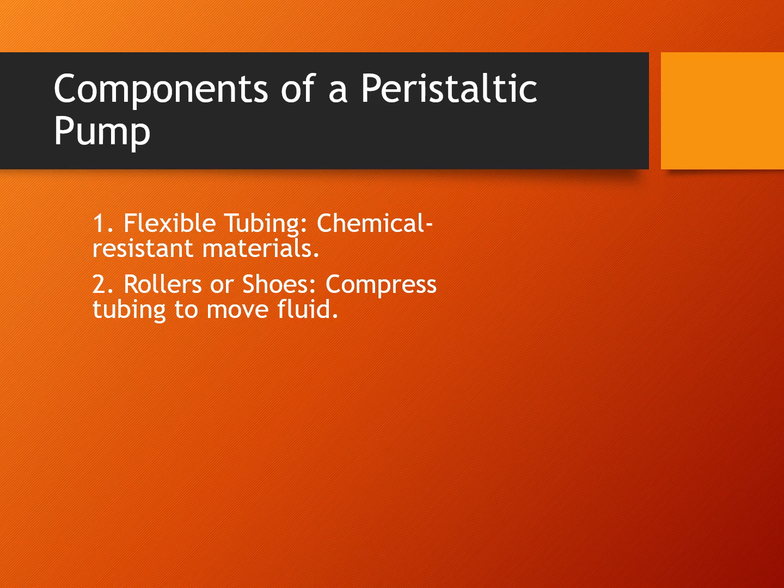You have the rollers and/or shoes. These compress the tubing to push fluid forward. More rollers provide smoother flow but increase friction and energy loss. So there is a trade-off there: as you provide smoother flow, it also encourages energy loss.